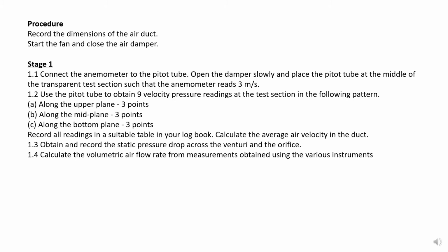Obtain and record the static pressure drop across the venturi and the orifice. Calculate the volumetric air flow rate for measurements obtained using the various instruments.